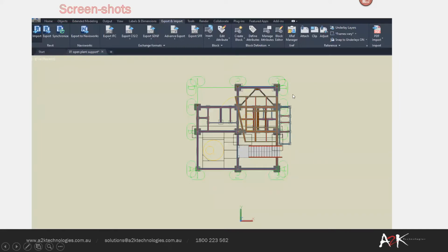And now this is the model in Advanced Steel. So we can see it here. It does have a UCS, which you can see. In Advanced Steel, you always try and draw to a localized datum point. Be aware that it won't really cope with world coordinate systems. It is always better to be based on a local 0, 0.